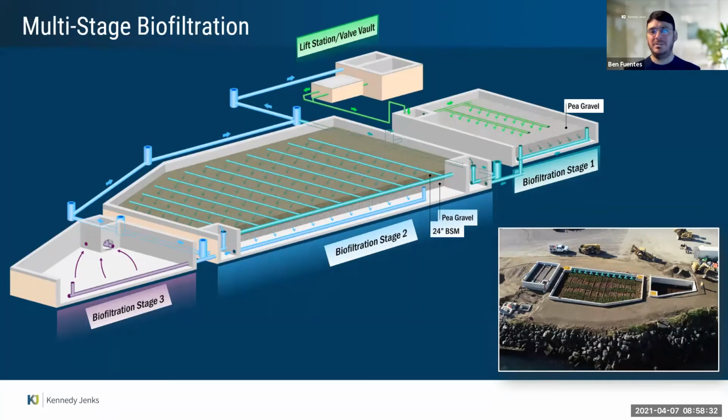The downstream stages, your biofiltration stage or your third stage, which might be a polishing stage, will likely have more expensive media. If it's biochar or coconut coir, things you don't want to burn through too quickly, you can have a front end stage that really knocks out those heavier solids and protects your downstream stages so that you don't have to maintain them as frequently.